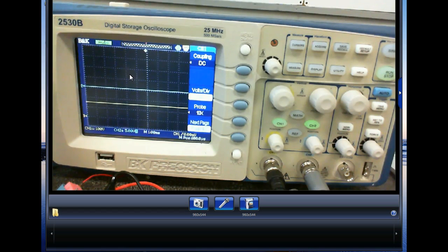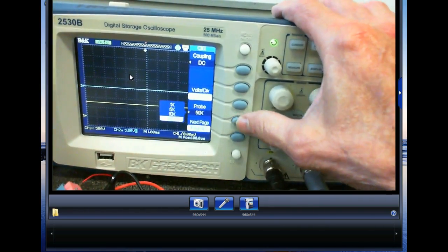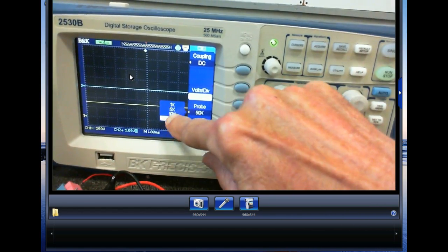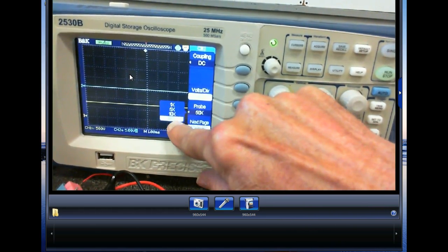It got the name times 10 from the analog scopes. We don't have the ability to do that. So it was called a times 10 probe because you had to make your measurement and multiply it by 10. On this scope, if you left it on times 1, you would have to do that. But if you put it on times 10, it automatically adjusts the ranges for you and attenuates the input by that, which is pretty neat. And you see it covers a times 10. I've never seen a times 5 and a times 50. The only thing we had at US Steel was times 10 and times 5.